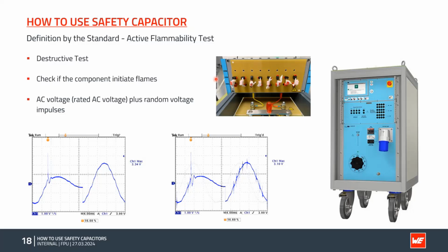When there is some breakdown and maybe some arc, the cheesecloth gets burned. In the worst case scenario, it really takes fire, it ignites. Then of course the test is not passed. This is something we have to check for the capacitor, regularly also to get the certification. So these are the most important tests for the safety features of these products.